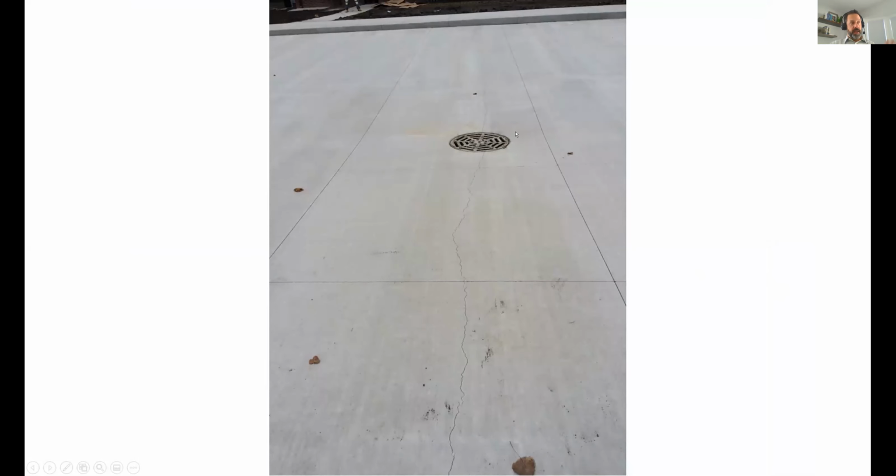Yeah, see, this is one in a parking lot where this is your initial point of stress concentration that very first night when that concrete's still fresh, whether the cuts are in there or not. That joint needs to be in there because that's the first place where it's going to want to start pulling away as that massive ribbon of fresh concrete is undergoing its hardening and shrinkage and everything else.